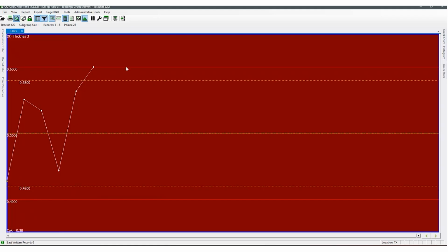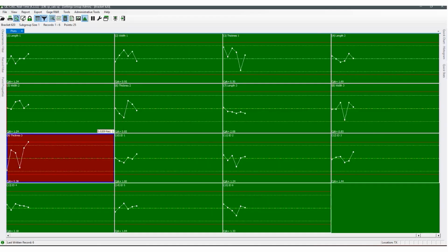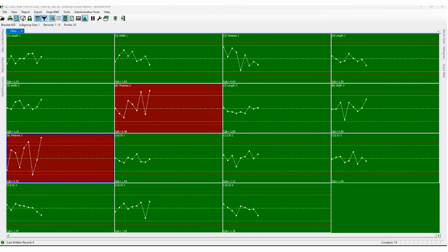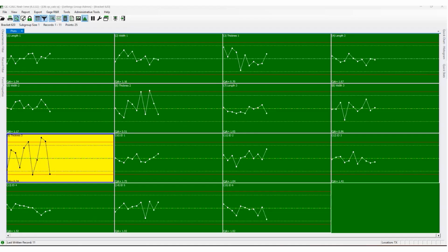It also shows in this chart not only the upper and lower spec limits, but the upper and lower control limits. Those can be calculated or entered manually, and they can be taught to be calculated automatically and then stop calculating after a particular period of time to fit the particular statistical rules that you are using at that time. I'm going to put in just a few more data points here. That yellow one that just flashed by meant out of control. And we'll note as we go further, that's an out of control one right there.